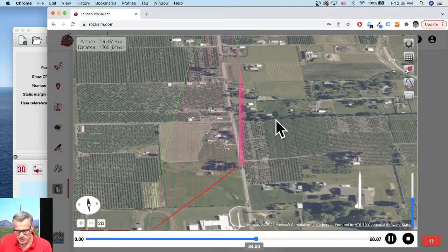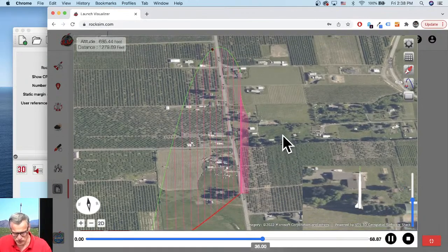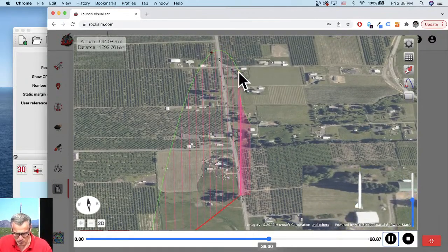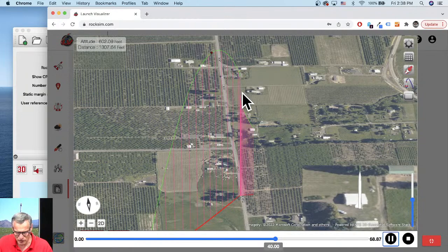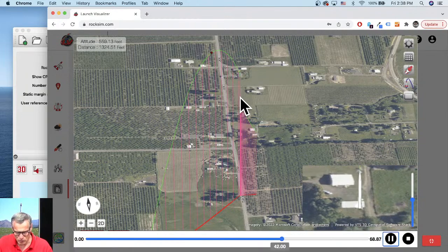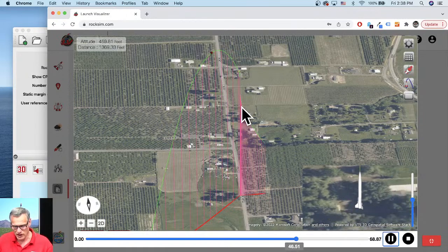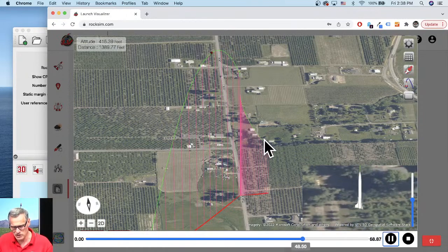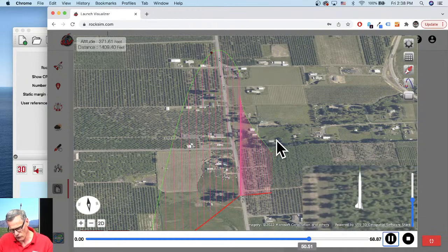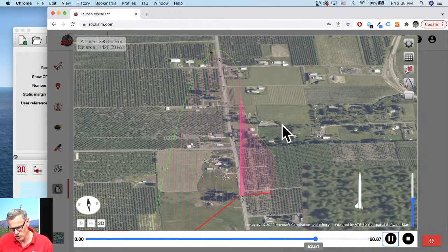And you can see, looking at this trajectory, that as soon as the parachute opened right here, it fell like a rock for a little bit of ways. It's because there was low wind speed, so it fell fast, and then it got into this higher wind speed, and you can see it's curved because it's not a constant wind speed blowing.